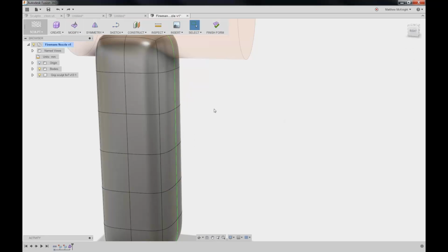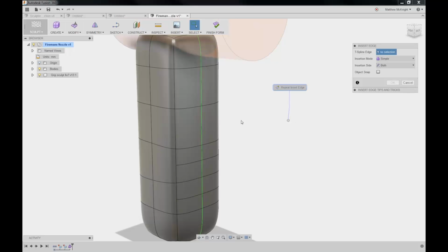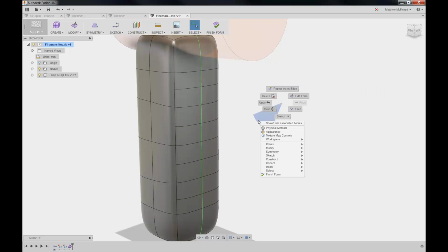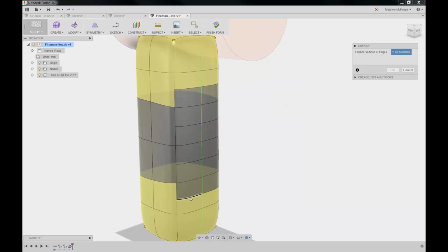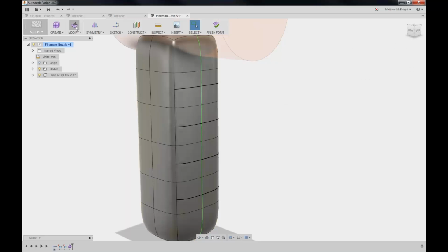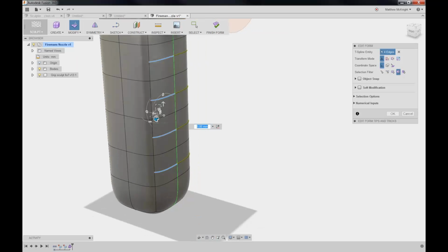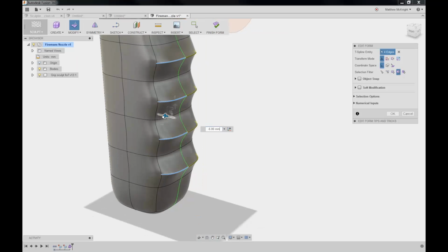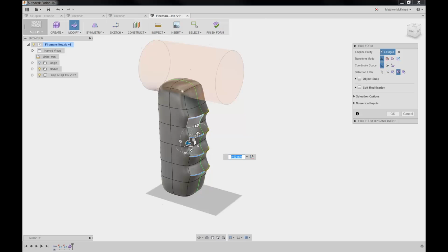So what we're going to do is, like we saw then, let's add those additional edges in place. So we'll grab that one, go OK, let's repeat it, that one, OK, and let's add the crease. Just quickly. Where are we? Want one. So 1, 2, 3, 4. Okay. Drag those out a little bit. I'm holding down the Control key to group select entities in that case, and drag these out in space. And you can see here that we've got now nice defined finger holds for our nozzle.